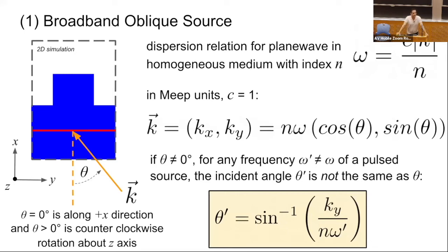Now, I think Numerical has a special feature called BFAST, where they support boundary conditions that can enable a broad bandwidth response at the same frequency. But from what I know, it has some limitations around stability and in use cases. And there's some very preliminary work, some discussions that we had to support something similar in Meep that we can talk about in the Q&A for those who are interested.